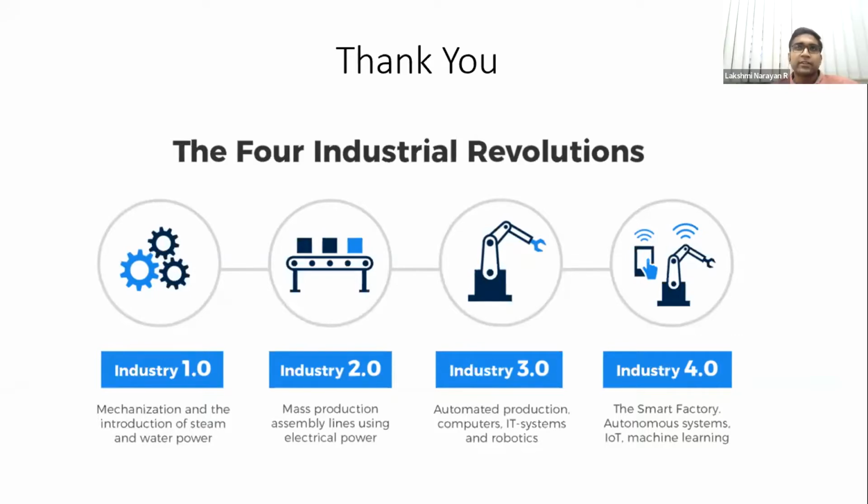Actually, yes. In fact, I didn't talk about another field I work in, which is WAAM. It's called wire arc additive manufacturing. Very nice method, very cheap, and for the Indian context, definitely something very exciting because it's much cheaper and something which we also understand very well. It's like having a welding torch and attaching it to a robot, and that gives you some excellent microstructures and very nice properties.